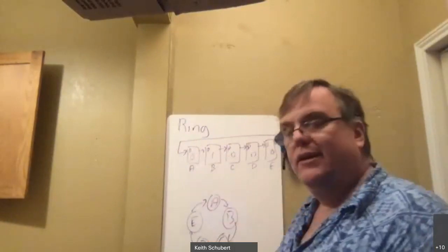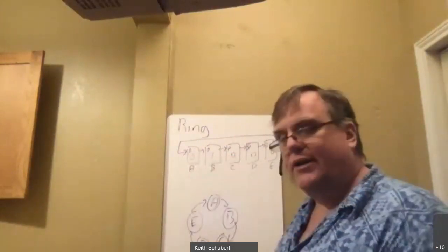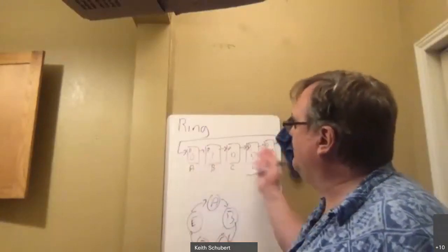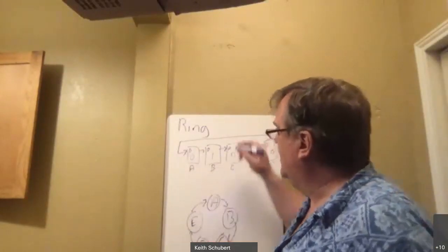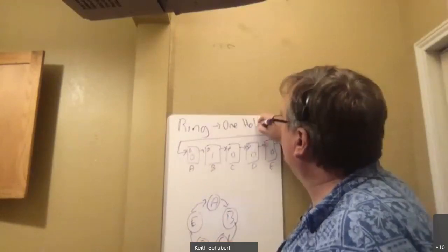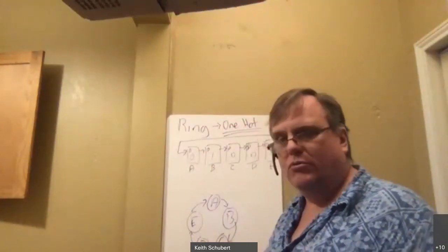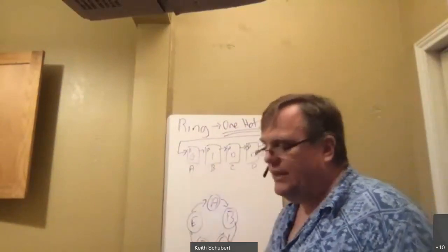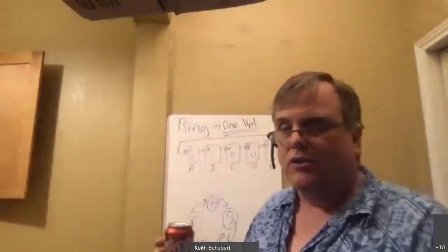It goes from A to B. No chance for an error, no weird intermediate states. They're all hooked on the same clock, and I just tell them to shift, and they go. So it makes a very easy, safe counter for this kind of one hot setup. So this is a really good setup for one hot. Very safe, very easy to build. Has a lot of nice features. One bit per state. So your only challenge is if you have a huge number of states, this can get a little bit cumbersome.